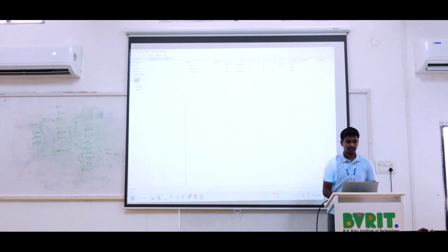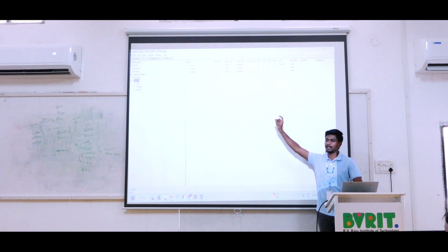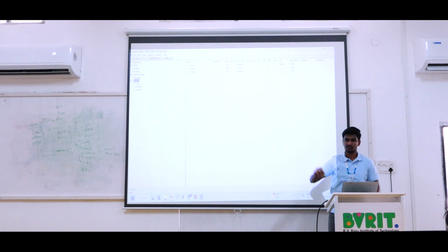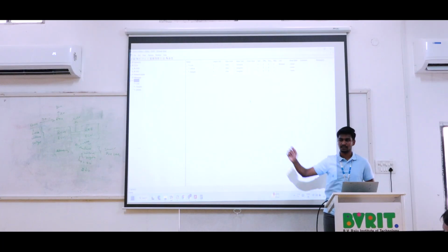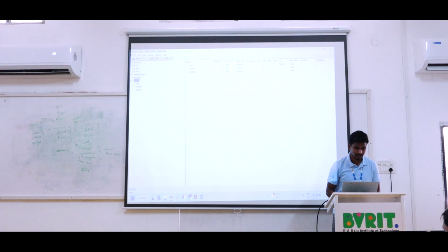So now we have created the three signals. Now we need to map the three signals to one ID number. The ID number is 400, as we have mentioned. The ID is called a CAN frame or CAN message. So now we are going to the CAN message, the message column. Just take the message and then we will see the format, the name, ID format, DLC, like that.